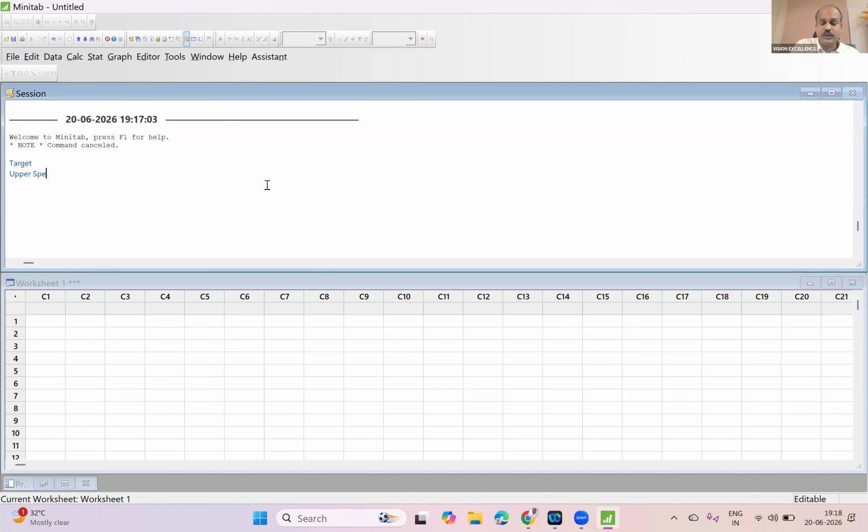There is an upper limit, which we call the upper specification limit, and he has a lower limit called the lower specification limit. It is nothing but a product characteristic. A simple example: it can be thickness. If the thickness is more, there can be interference. If the thickness is less, there can be a loose fit. Both can lead to product failure. Yes or no? And hence the failure at the product level.